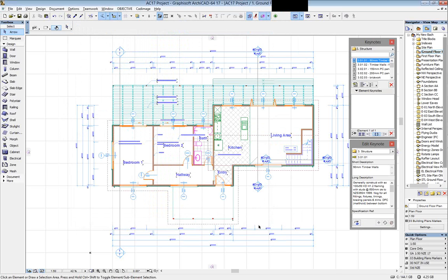As we work through the list here, I'm on page 89. Linked elements, new feature in ArchiCAD 17. All I've done there is said wall and columns are now linked to the story above. So if you change your floor-to-floor height, these things move with it. Floor plan display, basically there everything's set to home story only except for the stair tool, at which point you want the stair to show on the home story and one above. Design tool defaults, floor plan and settings there on page 89, so I've run through all those.